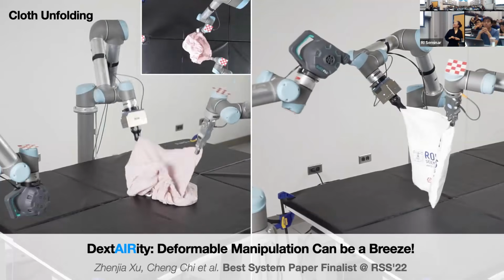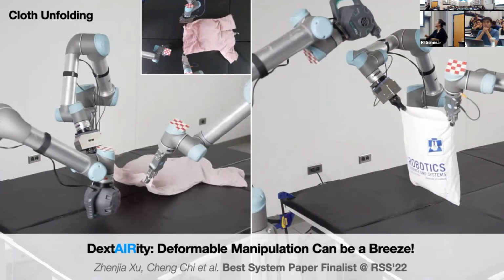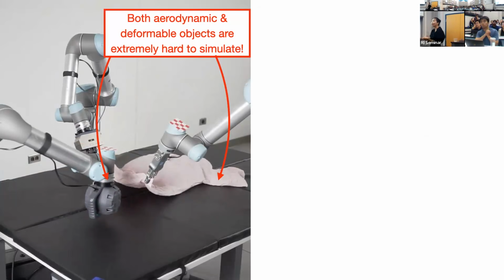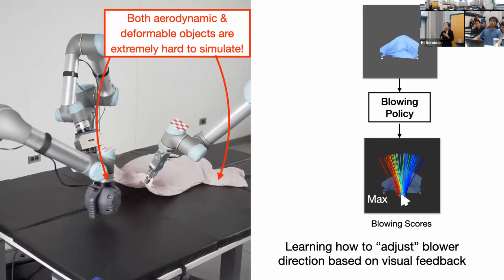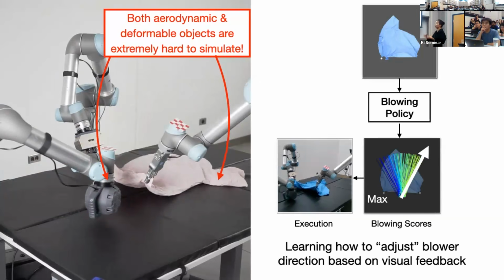A good example for that is air-based manipulation. In this project, DextAIRity, we're trying to make the robot manipulate deformable objects by using active air flows. If you think about it, both deformable objects and aerodynamics are things that are extremely hard to model, and it's going to take very expensive compute to model them precisely. But what we found is that instead of trying to learn a dynamics model, it's much easier to train a closed-loop policy that learns how to adjust, for example, the blower direction based on the visual feedback. And that is a much more effective way to learn an effective policy to, for example, unfold a piece of cloth. Right?